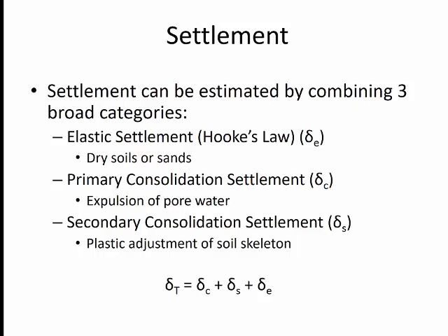The next one listed is primary consolidation settlement, and that is when we have saturated soil, often clay material in nature, and the saturated material oftentimes does not allow the water to expel or travel through the soil structure very easily, and so it takes some time, and so we really want to understand this property specifically, and that's what we're really going to focus on with this experimentation.